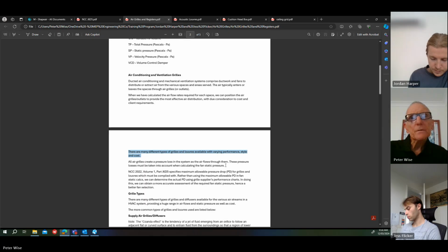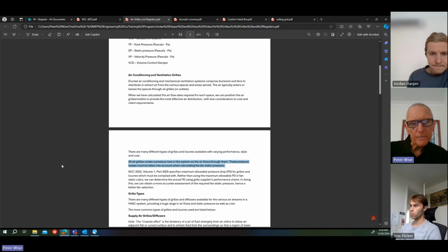All air grills will create a pressure loss in the system. Last week we talked about fan static calcs. So you've got to consider within your index run, which is your worst case pathway for the air, you've got to include the grills.